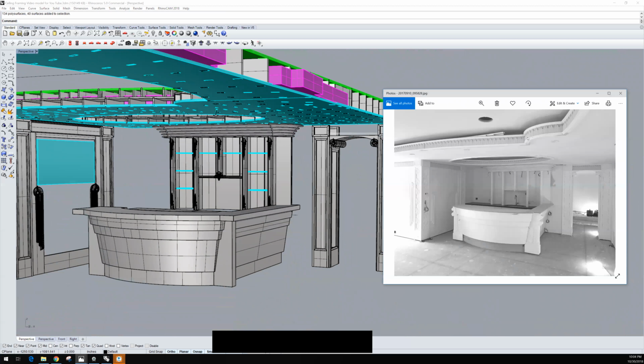So you can see this is the J.P.Weaver molding that was put in between our upper and our lower molding. All of these pieces of molding, the ones that travel around the large soffitted area, and then the oval in here, were cut on the CNC, and we even cut the miters, both top and bottom. So what we did is we dry fit all these pieces, held them up with clamps, and moved them around so that all the miters lined up correctly.